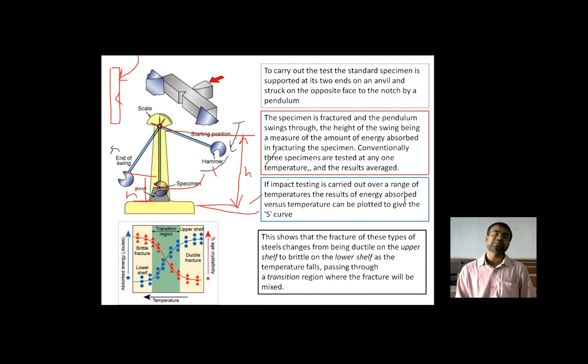So all the tests are taken care of by the ASTM standard, and should consider the temperature scenario in which this particular transition is taking place. So the upper shelf position of the material transition is very important. When the material temperature goes down, moving to the lower shelf, the particular material will change its behavior, and the failure of the material will take place.